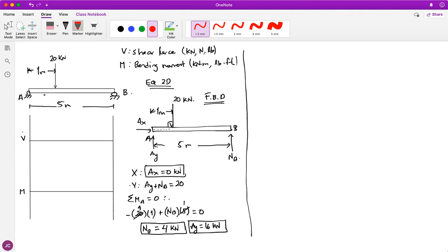And you will say, okay, so I got it. Now what? Well, now the criteria, my way of saying this criteria of putting section is put one before and after a disturbance. So let's start with this pin support, okay? If the criteria says put one before here, well, there is no beam there, so it's just trivial to put one over there. So I won't put one before the pin support, but I can put one after the pin support, whoop, like that, okay?